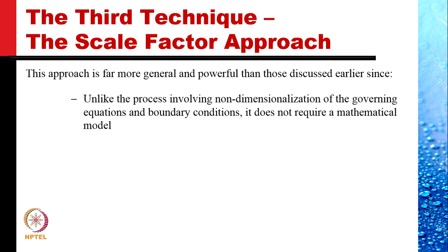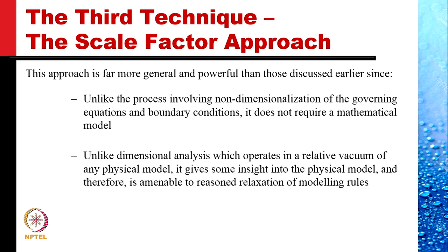Unlike the process involving non-dimensionalization of the governing equations and boundary conditions, this approach does not require a mathematical model, and that is a lot of saving. And unlike dimensional analysis, which operates in a relative vacuum of any physical model, it gives some insight into the physical model. Not the whole insight, but some insight, and therefore is amenable to reasoned relaxation of the modeling rules.